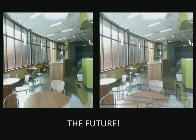Here's the Davenport Library, the pictures of which we've been looking at. And you can see on the left picture, this is what it looks like finished. Here's the register grills pumping in the supply air at a low elevation. And on the right side, we've sketched in some of our ductwork. So you get an idea of how the ductwork's traveling underneath the slab, underneath the ground. Corrosion's not a concern for us, and the customer never even realizes the ductwork's there, as it should be.